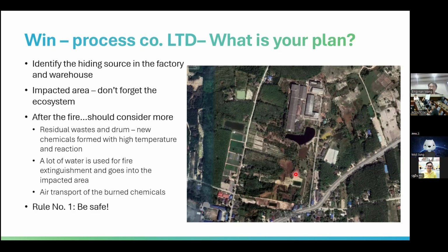That might save you some money and give you better resolution. Also, one thing you can consider is the high resolution site characterization. Instead of sending samples to the lab, if I want to understand the concentration of heavy metals, for example, we can use XRF to scan through the site or the cluster and get a better resolution.